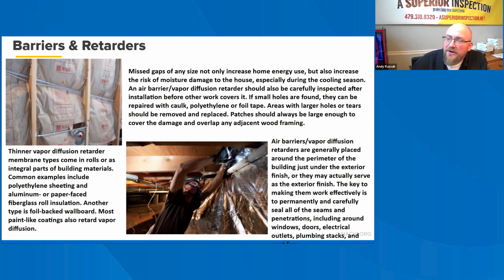In many cases, air barrier and vapor diffusion retarders consist of one or more of the following materials: polyethylene plastic sheets, builder's foil, foam board insulation, and other exterior sheetings. Moisture is a common cause of building degradation. In fact, much of what we know about applied building science today originates from early work investigating moisture impact on buildings. While the severity of moisture problems varies greatly depending on climate, few regions in North America are free from concerns about moisture in buildings.